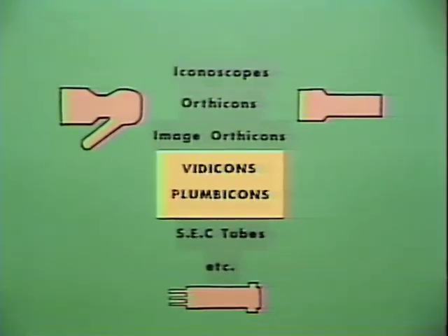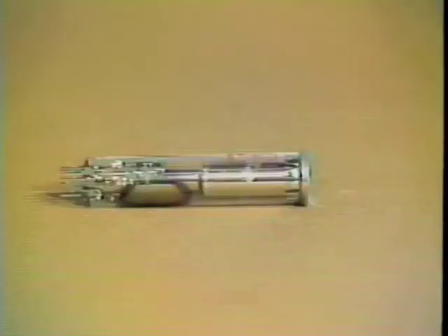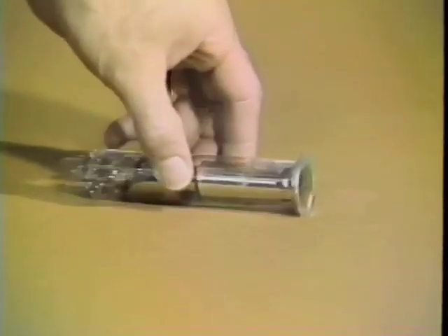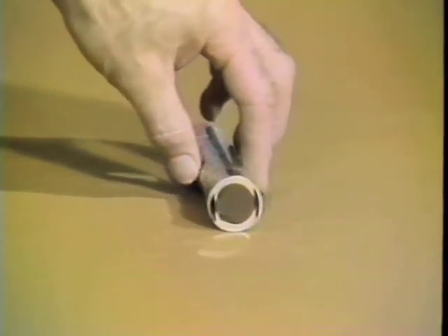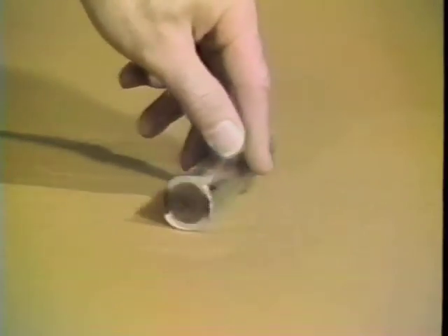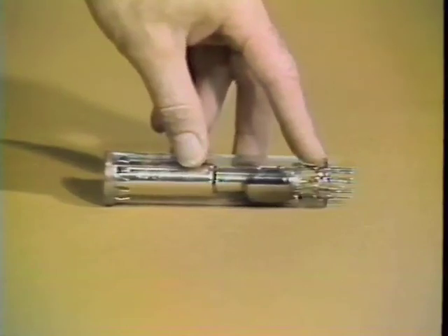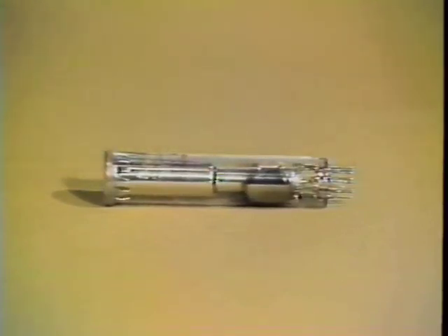The early tubes were called iconoscopes. Later there were various types of orthicons, image dissectors, and a low-quality tube called a vidicon. Because it was so much simpler and smaller than the other tubes, the vidicon was very attractive, but it was not until about 1960 that it became a high-quality tube good enough for broadcast. The plumbicon is a special type of vidicon. As almost all tubes in use are now plumbicons or vidicons, we will concentrate on how the vidicon works.